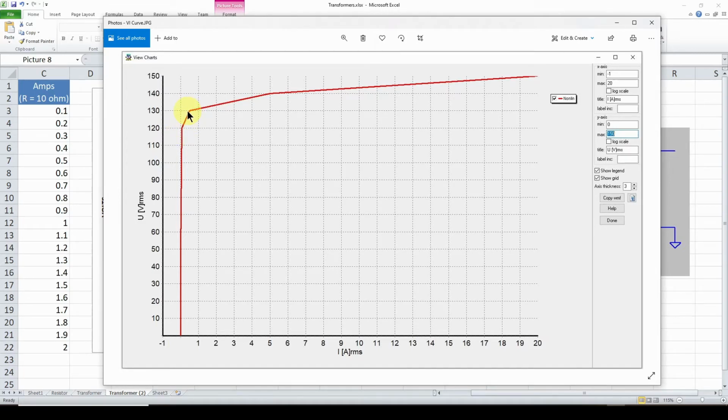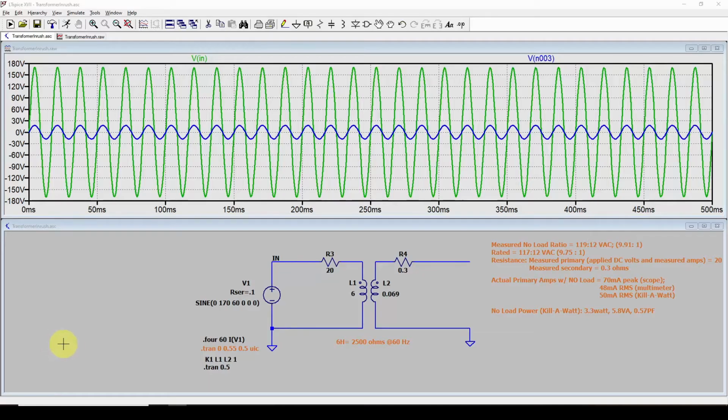But when you're getting much above 130, like 15 or 20% over, now you're starting to get into much greater than it's rated for. And perhaps the curve is going to look like this, and suddenly for a small increase in voltage, you get a big increase in current, right? So this is just my guesstimate about what a voltage versus current characteristic would be like. And if we can enter that into our simulation software, we can have a pretty good idea of how it's going to respond at higher voltages.